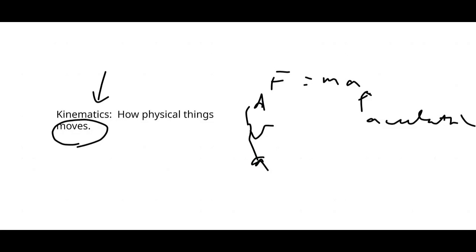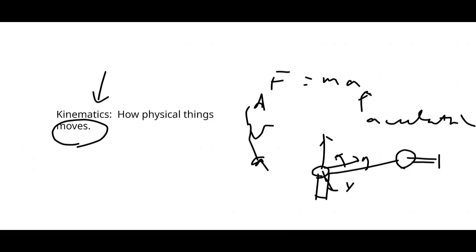So this diagram is related to how your robot moves. You have a theta, you have the XYZ axes, and also related joints, revolute joints and prismatic joints. The diagram represents how things move and what the control variables are: theta, the XYZ, the displacement d, and the alpha angle.